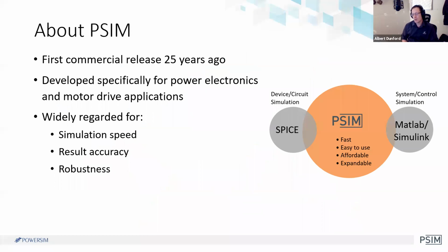When you turn a switch on or off, an IGBT, MOSFET, or what have you, that introduces a derivative into the voltage and current waveforms, and that derivative can cause issues with regards to convergence, without naming names of competitive tools. That transition and those derivatives can cause problems.